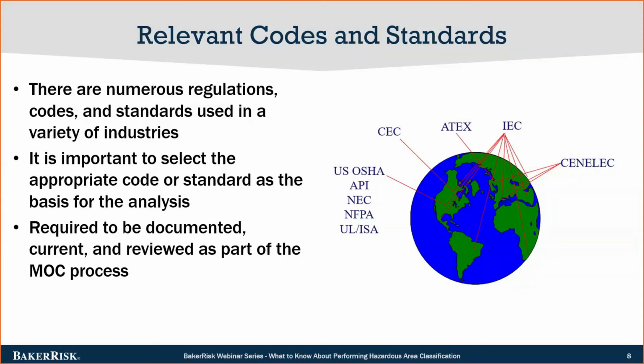It is very important to select the appropriate code or standard as the basis for this analysis, because while they contain a number of common areas, there are some differences. Above all, these codes and standards require that the hazardous area classification be documented, that it's current, and that it's reviewed. And we suggest it's reviewed as part of the MOC work process.